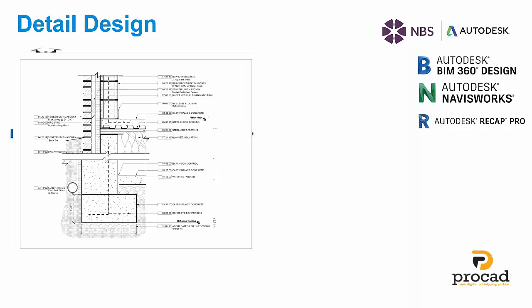it will replicate wherever you place that material again. So Revit also has quite powerful 2D details, so you're able to cut through your BIM model. You can add in 2D information for whatever reason if you want on particular 1:5 or 1:10 details, but all the tools are there to be able to create 2D and 3D details as well.